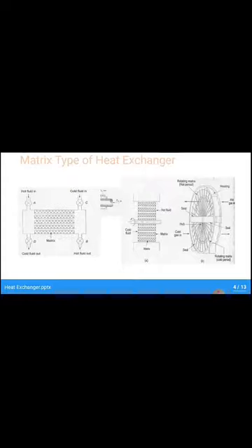It means that at first, for 1 minute, let us say, hot fluid comes inside the heat exchanger, goes through the matrix and flows to B. This happens for 1 minute only, just as an example. While flowing, the matrix collects energy from the hot fluid, and the hot fluid loses its temperature.